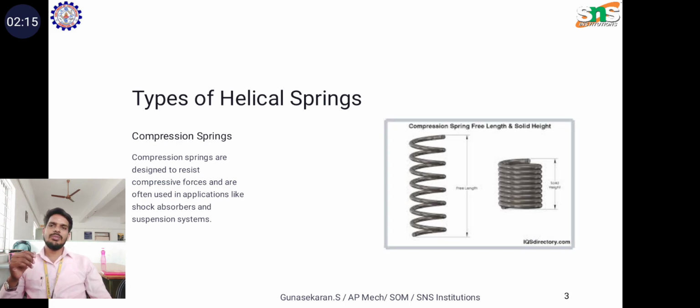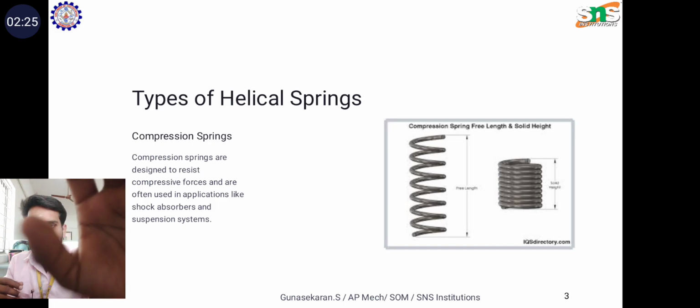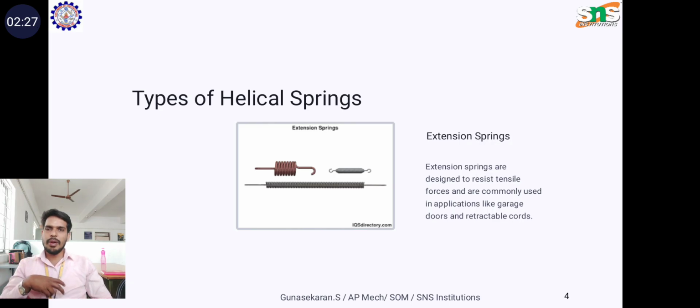Design consideration means we mainly focus on how wire diameter, coil diameter and pitch influence spring rate and load capacity. Okay, we are seeing the second one, the extension spring. It is a helical spring designed to resist tensile force when pulled apart.